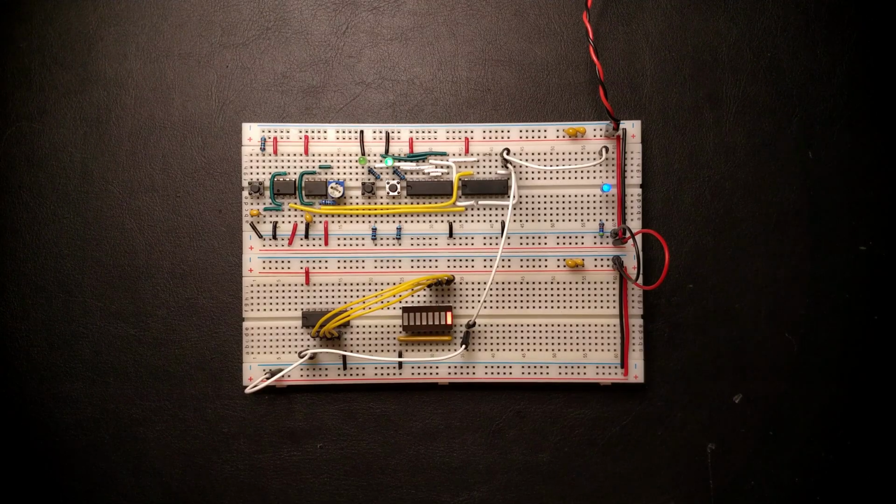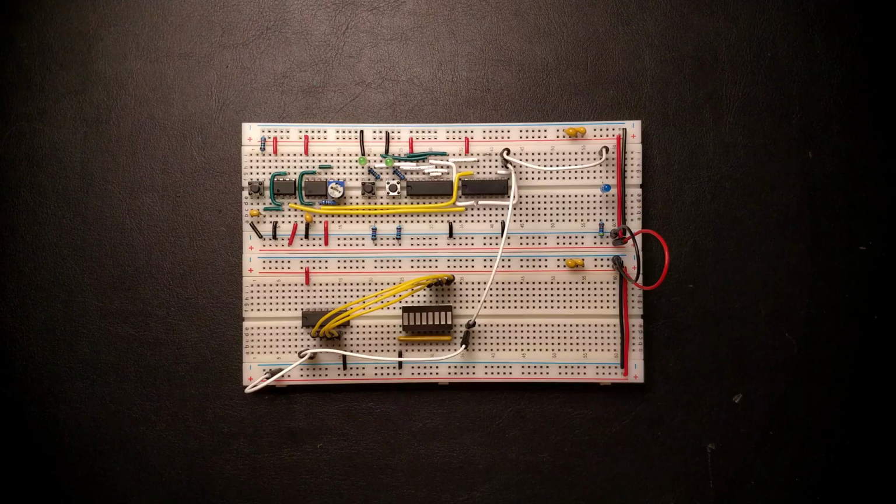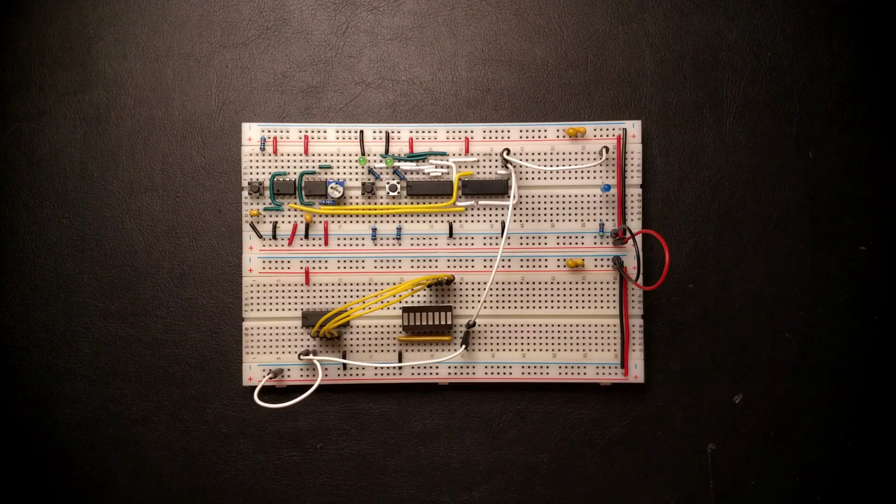But we're not entirely done with this breadboard yet. With our nice clock generator all set up and working, there's one last topic we need to look at, and that's resetting our CPU. Many of the storage chips like flip-flops and counters, which we'll use throughout the CPU build, have a dedicated signal to reset them to a known state.